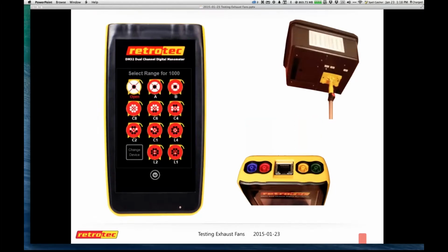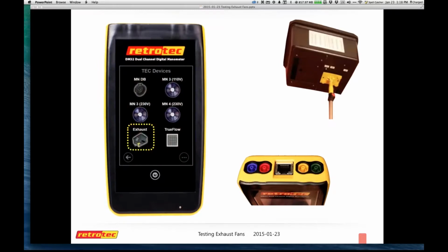So in order for you to measure the amount of flow, the amount of CFM, you must know the pressure and you must know the size. If you know those two, you can determine your conclusion. On the bottom here, I now have selected the exhaust fan flow meter, and it's on the range E2. I think the image may have E1. That's E3, so the image doesn't actually match, but I wanted to go through the exercise.